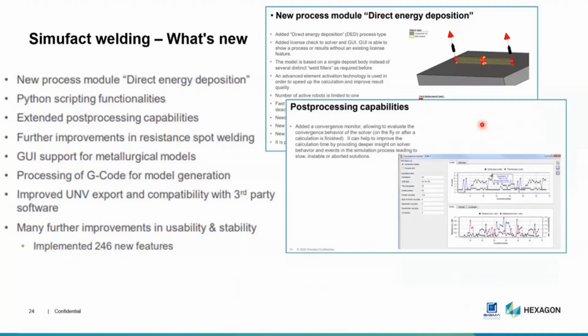Runtime is a challenge when it comes to welding, so now you can monitor which iteration takes more time and what the challenges are, through process capability and solver time monitoring, so that you have a clear understanding whether it is heat treatment or welding at a particular location that is taking more convergence and what could be the reason for that.